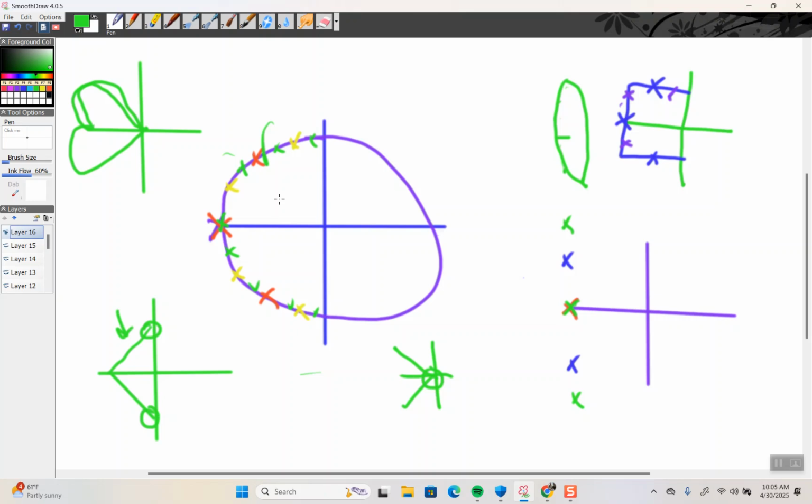I think the wizard has high pass, low pass, and band. It doesn't do notch. And I think what you do if you want a fourth order notch is you do a second order high, second order low, and cascade them.